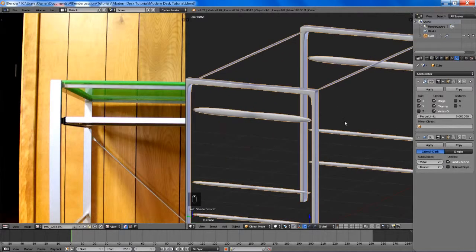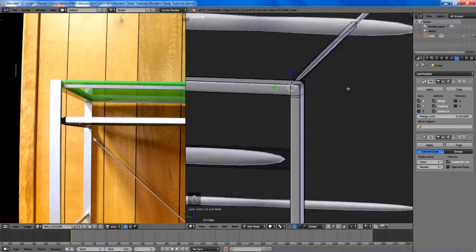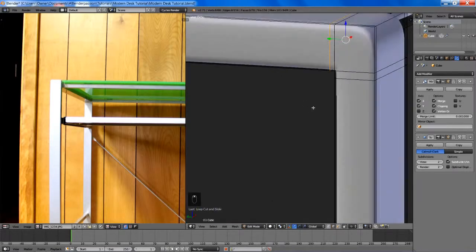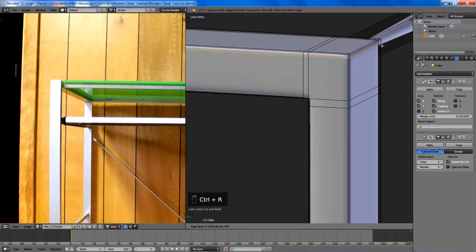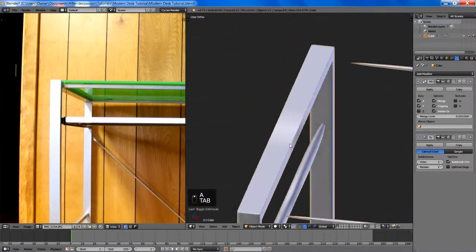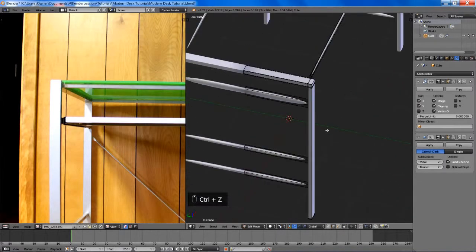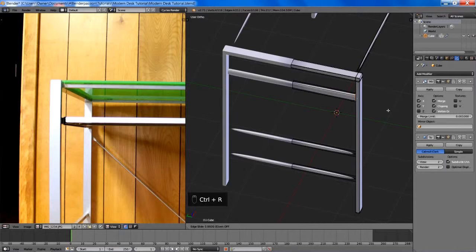So now I'm just going to keep adding them in until I can see that all the edges look nice and sharp. And it looks like this needs another edge loop. Right here looks good. And you see we have this rounded off corner here. I'll just fix that. So now we are getting a few artifacts where the mirror modifier is. So for now, I'll just maybe add some edge loops right to the middle there. We'll fix all those artifacts after we apply the mirror modifier.